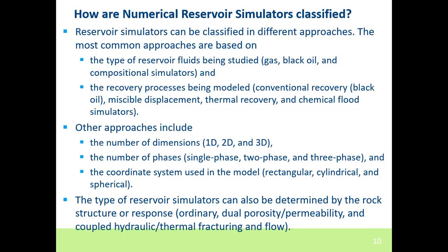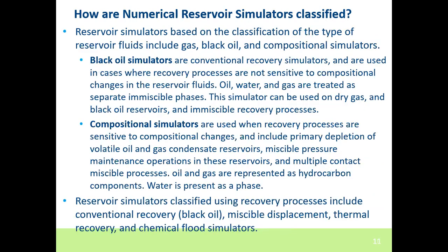Is it a 1D model, a 2D model, or a 3D model? Number of phases, the coordinate systems you want to use. The type of reservoir simulator can also be determined by rock structure or response. Is it a typical single porosity system, a dual porosity permeability model, or one coupled with hydraulic and thermal fracturing? So these are considerations that need to be made.